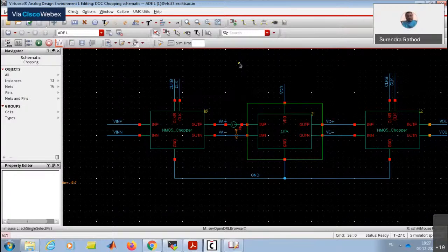Okay. So which technology are you using for this? 180 nanometers. What Professor Mariam presented was the same 180 nanometers. It is fine at 180 because our chopping frequency is hardly 10 kilohertz. So this technology is pretty good. Even the same technique you can use to simulate RF circuits, mixers and all. So PSS, PNoise. There is also one PAC analysis, which is equivalent to normal AC analysis.